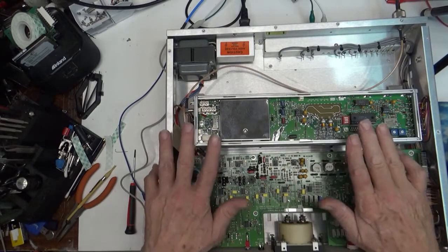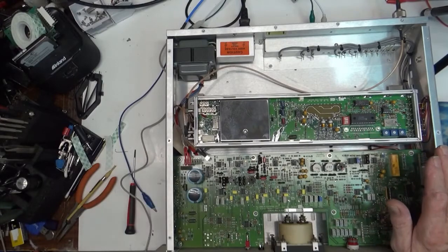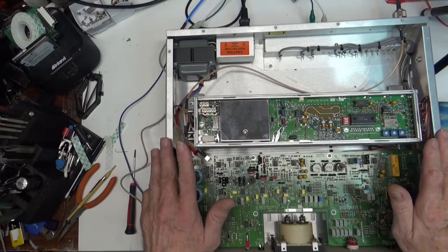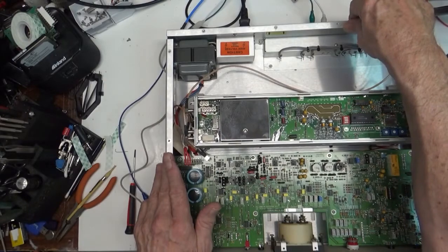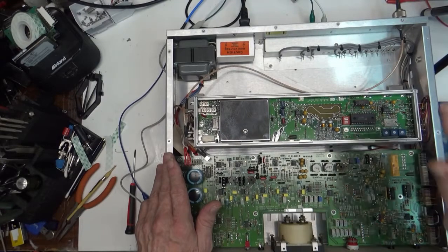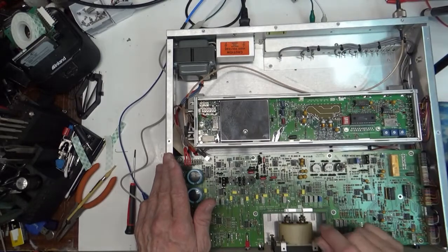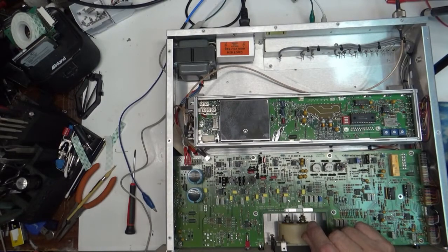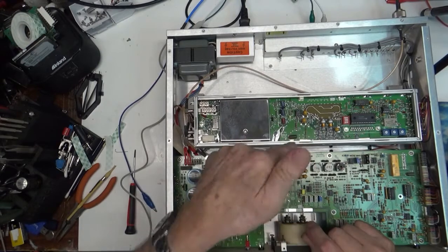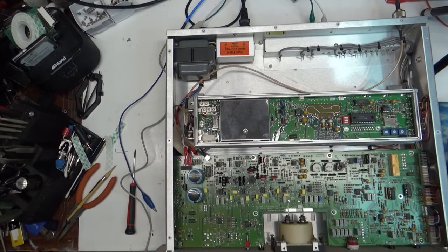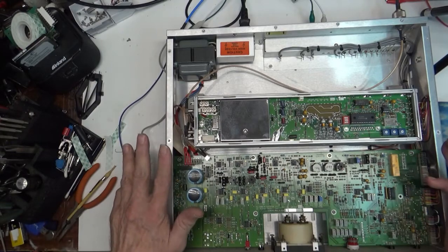So, what we've proven is that the transmitter transmits on the right frequency, the receiver receives on the right frequency, the mux signal goes through like it's supposed to, and on 26 kilohertz, and that our audio is clean, coming from the transmitter through the receiver and into here. That little generator I've got, that 0.2 is about the best it'll do. They're not that clean. They just aren't, but that's what I got over there because I had to feed it 2 signals at once, and that thing will do it. Anyhow, that's how you do it.